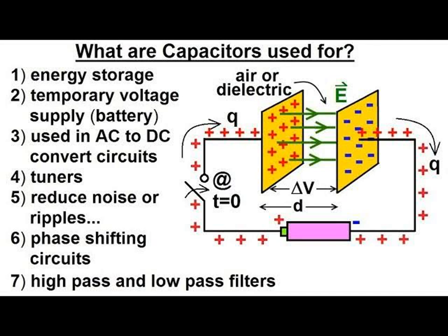Now that takes us to the last guy, which is the electrolytic capacitors. Electrolytic capacitors are very similar to fixed capacitors. It consists of two long aluminum foils separated by a cotton material called muslin. When the terminals of these capacitors are connected to a DC battery, a thin coat of aluminum oxide is formed at the anode, which serves as a dielectric. That means once you connect it to a DC voltage supplier, a thin coat of aluminum oxide is formed at the anode. And this thin aluminum oxide serves as a dielectric material because it does not conduct.